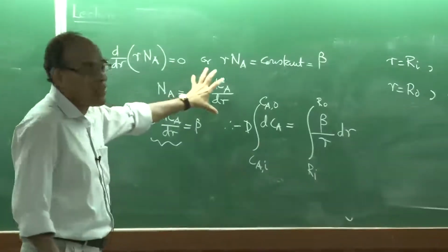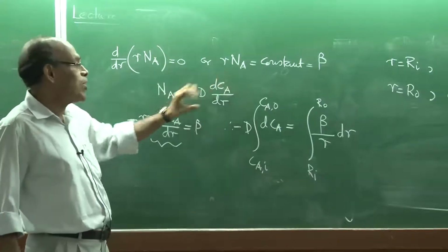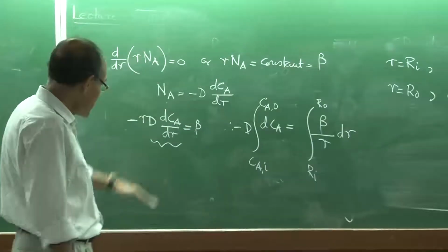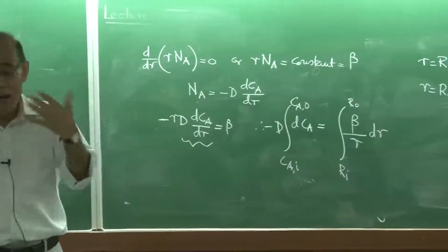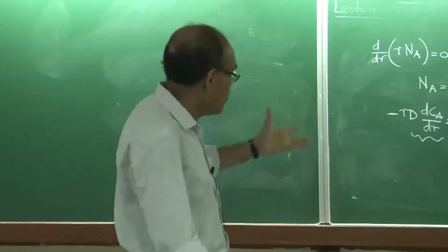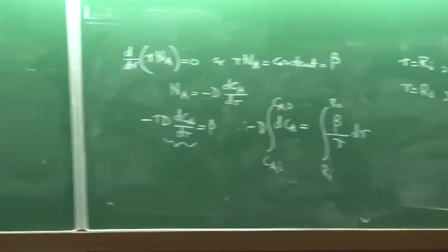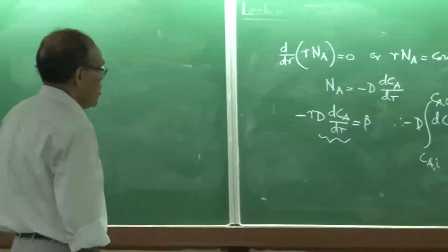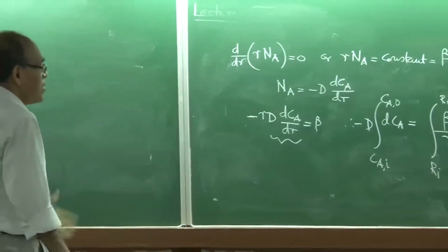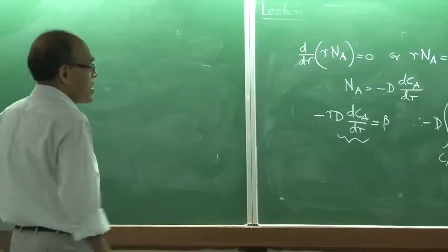So the governing equations, the diffusive mass transfer equation and the heat conduction equation, are going to be absolutely identical. Therefore, whatever I am doing here and the results that I am going to show will be applicable to a corresponding heat transfer scenario on a one-to-one basis, with diffusivity to be interpreted in terms of, for example, thermal conductivity, because it's a steady state problem, there is no rho, no Cp, which is associated with unsteady state heat transfer.